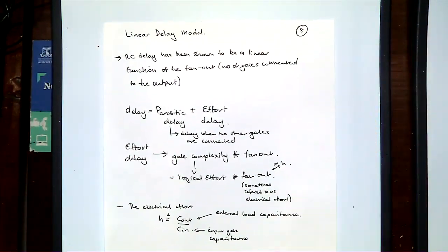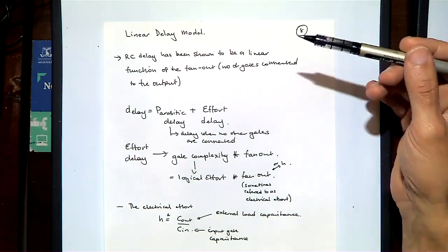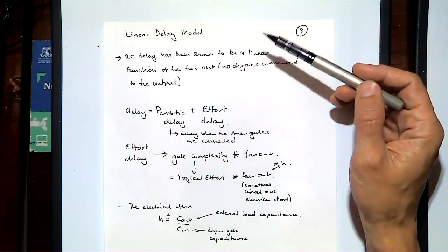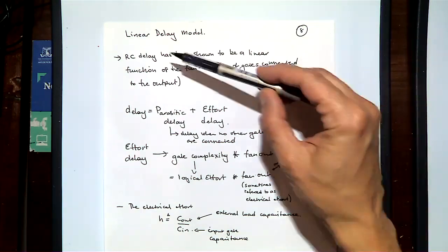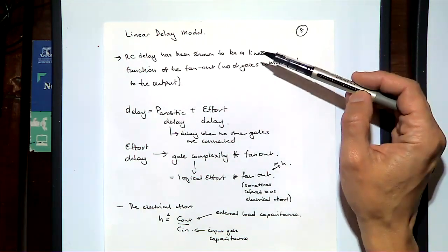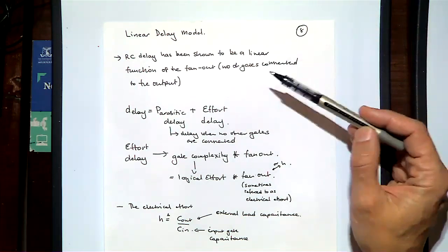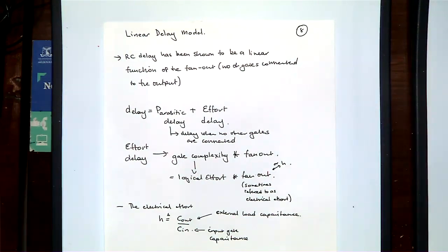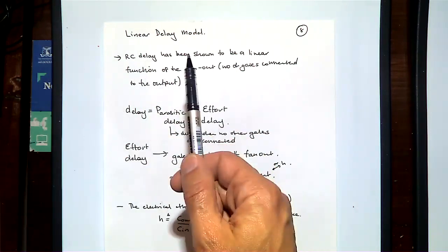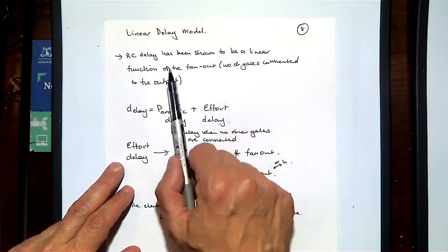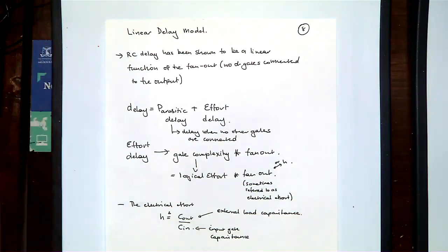Work at this linear delay for these much more complex circuits. So what we've shown so far is the RC delay is a linear function of the fan out. If you remember the NAND gate we had connected, or the inverter, and we connected in inverters. Essentially, what we said is that RC delay depends on how many of these other gates we're actually trying to drive, right?